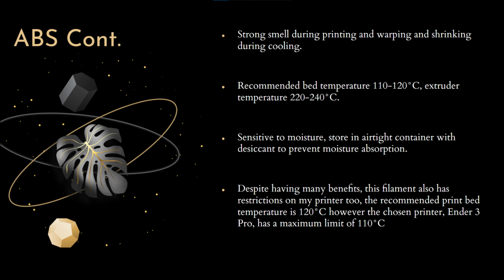However, the use of this filament is heavily restricted. Many printers are unable to print at these high temperatures. For example, my Ender 3 Pro cannot print with this filament as the bed temperature needs to be between 110 and 120 degrees Celsius. However, there's a limit of 110 degrees Celsius for the Ender 3 Pro's bed.